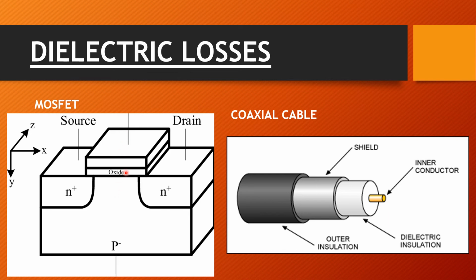Also, the oxide layer is important in order to isolate adjacent devices. As you know, in a chip or any kind of IC, the transistors are very closely packed because we want highly sophisticated functions out of a single chip, and there are millions of transistors in a chip. They are very small in size, very densely packed, and the chip is very compact, so oxide is definitely required in order to provide insulation.